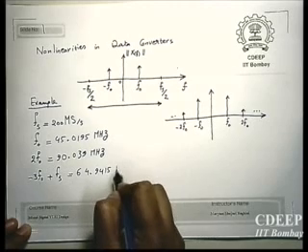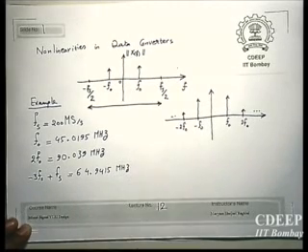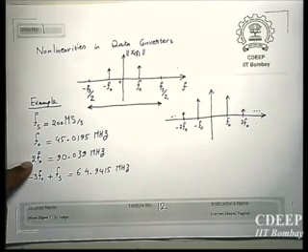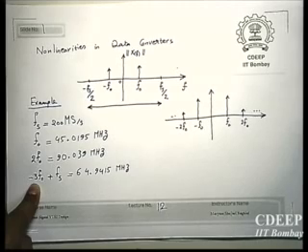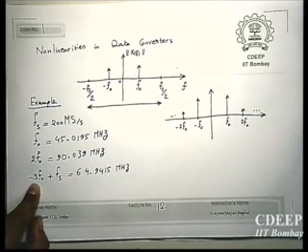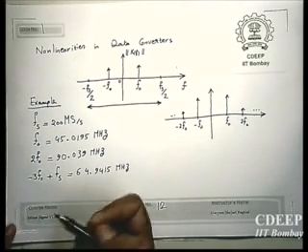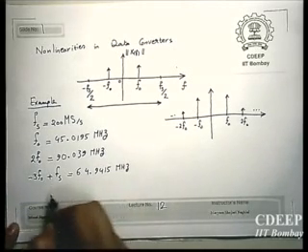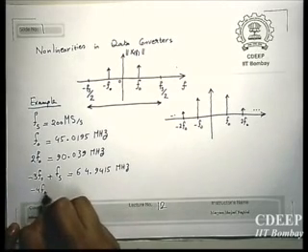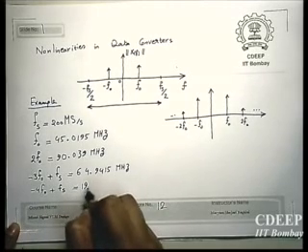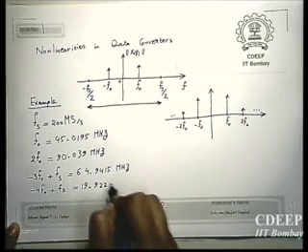64.9415 megahertz. So therefore, first harmonic, second harmonic, third harmonic is a folded version of third harmonic which has come by frequency shifting of fs. It is folded to the main band. And now continuing with that, for example, minus 4f0 plus fs, that will give you 19.922 megahertz.